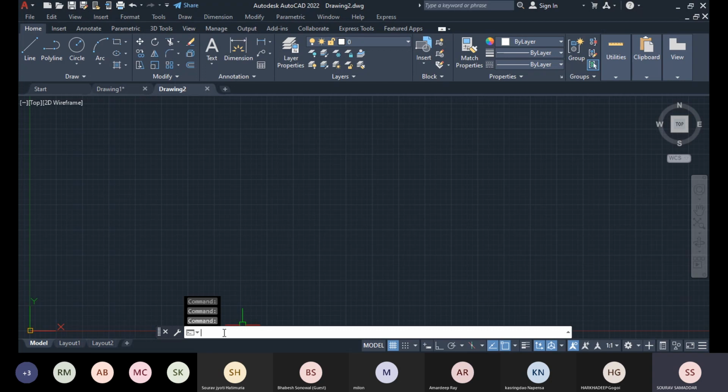That's why the basic and first option that we need to apply in any drawing is the limits command. What is the command? Limits. Limits denotes the starting point of your drawing page as well as the closing point of your drawing page. Likewise, you can notice the dimension of your page, that is 12 by 9. First one, that is limits. See, I already entered the limits command.